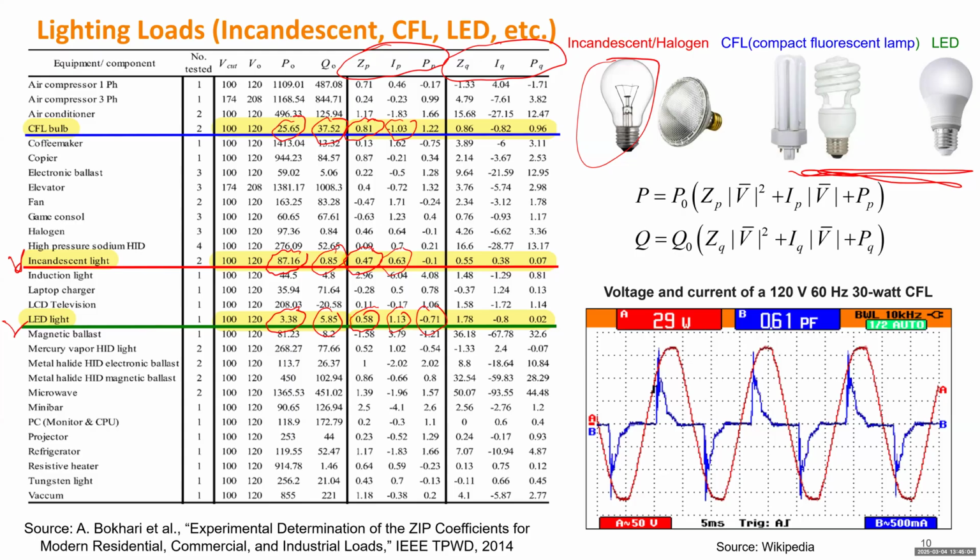I use this example to explain why those energy saving lights can have very large reactive power. What does reactive power really mean? If you draw the voltage waveform at this bus or substation, that voltage waveform can be controlled by a controller. If it's next to a generator, the generator will generate a perfectly sinusoidal waveform, if this generator is designed well. When you connect a load to this bus, the voltage cannot be changed significantly, but the current can change.